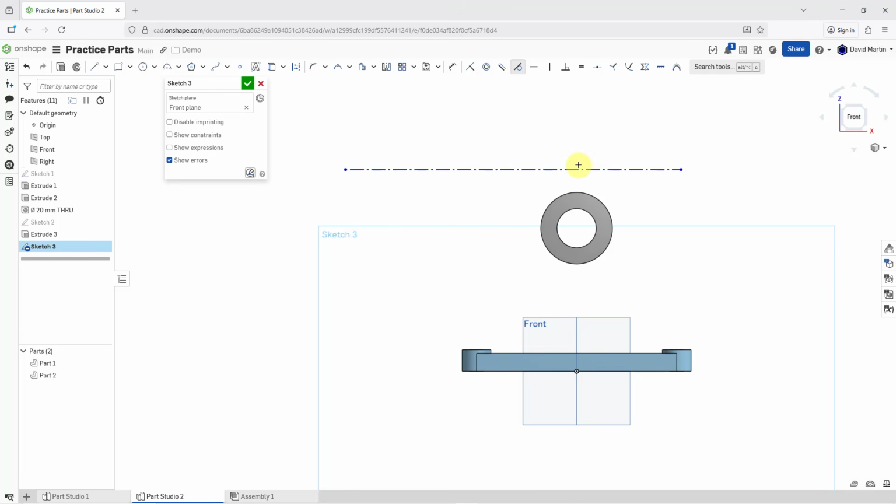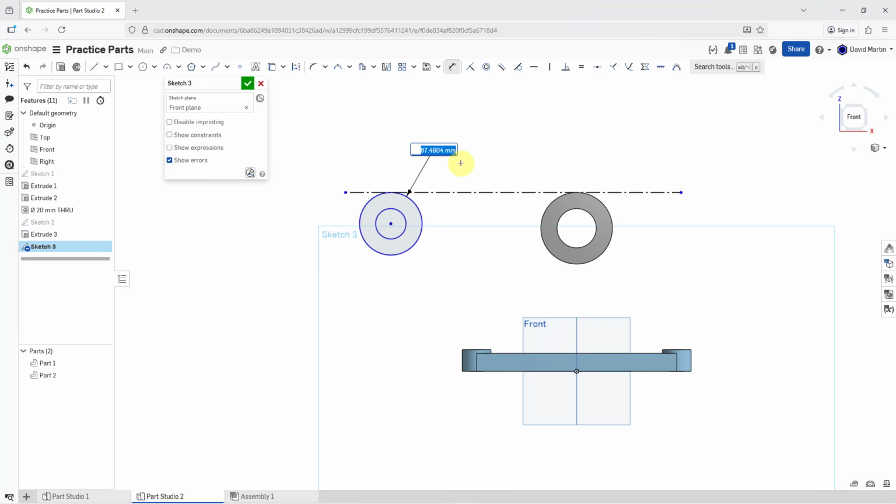And now let's make the line tangent to the circle and create our circles for the cylinder that's going to hold the clamps over on the left. So let's go to the circle command and let's drag out one circle and let it snap in there, and then another circle and make it about yay big. And so these circles are going to have diameters of 75 and 40. Pick this, drag it out, make it a value of 40.